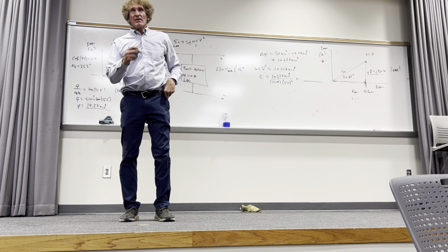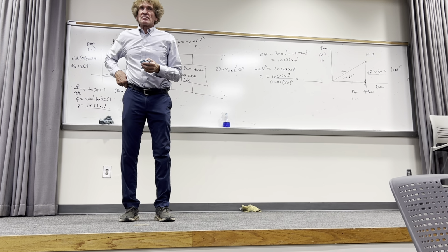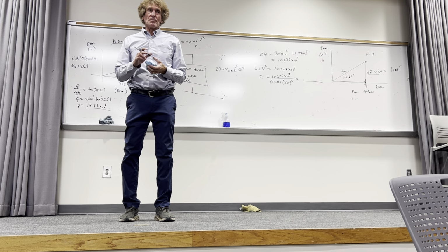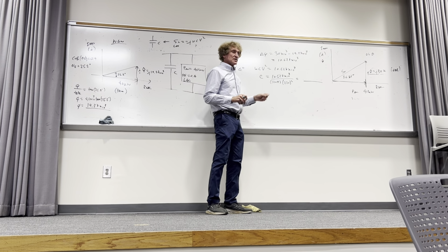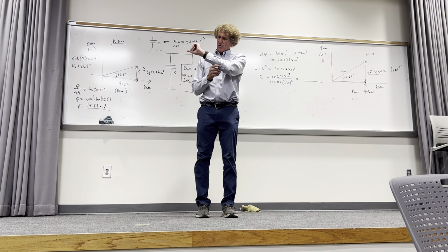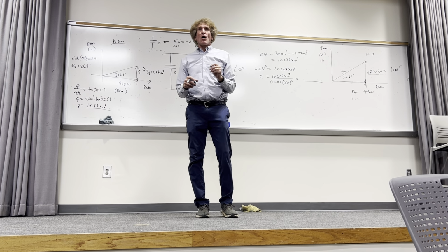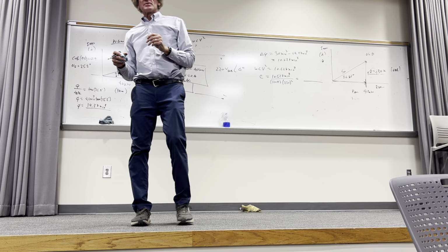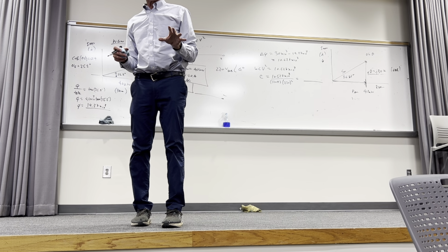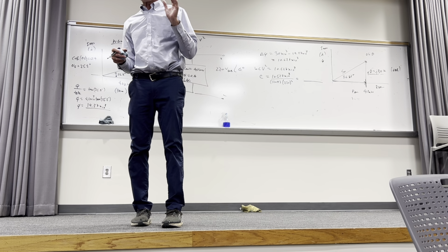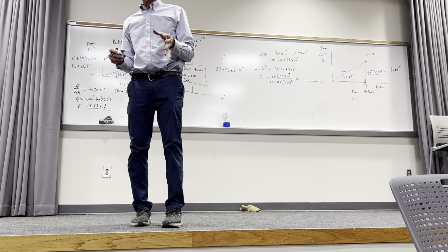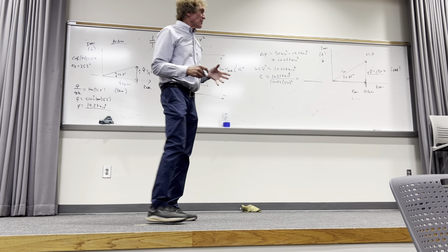The second thing is this voltage and the current are all RMS values. They're not peaks. It's very important to keep that in mind. Now, I'm not going to try to trick you. If they're power-related problems, they will be RMS values. You're with me on this, class? There's no tricks here, but you have to understand.